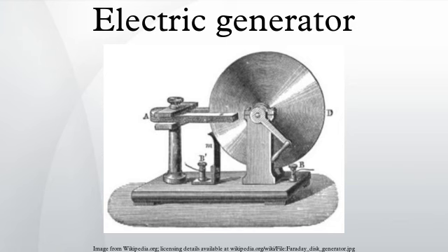Excitation. An electric generator or electric motor that uses field coils rather than permanent magnets requires a current to be present in the field coils for the device to be able to work. If the field coils are not powered, the rotor in a generator can spin without producing any usable electrical energy, while the rotor of a motor may not spin at all. Smaller generators are sometimes self-excited, which means the field coils are powered by the current produced by the generator itself.